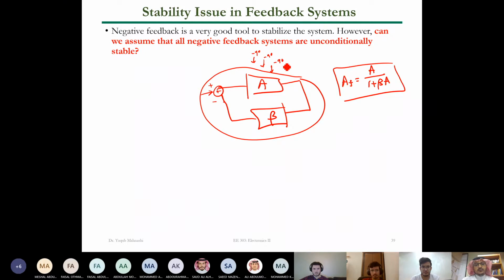versus frequency, right? The phase changes with the frequency. It depends on the frequency. If you are applying a low frequency or high frequency, the phase depends on the frequency you're applying. So imagine, of course, we have a range from 0 to minus 270 here. So imagine a case where you hit, and I cannot change the colors here, I don't know why. If you can find an omega, which is a specific frequency, that will give you a minus 180 degrees in the phase of the loop.